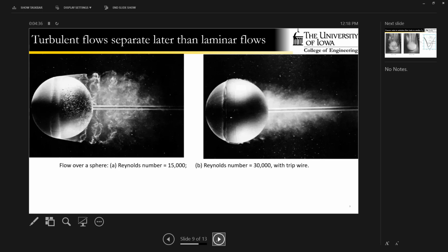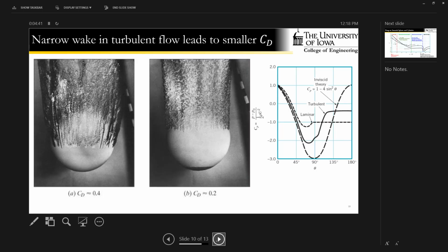So the kicker is that turbulent flow is actually much better, or it actually reduces the drag coefficient of a body when it's a bluff body. Okay. Turbulent flow is lossier. We talked about that. The drag coefficients in turbulent flows due to friction are higher. So you're paying some penalty if you have turbulent flow. You're paying some penalty in terms of the shear stress, okay, that friction drag. But you're saving so much drag in the pressure drag because you've minimized the region of this low pressure wake that you make up for it.